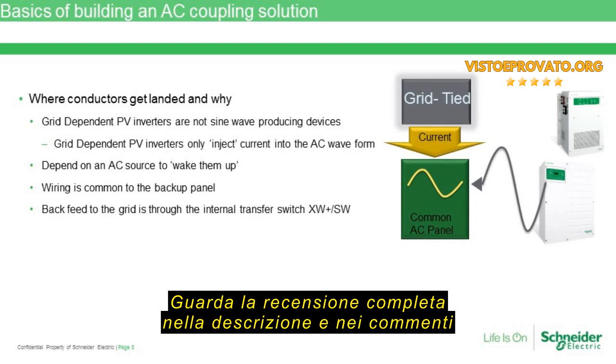then that grid tie inverter can start experiencing a frequency shift. And this is actually done on purpose by the XW Plus. So as the voltage on the battery starts to rise, the XW Plus is actually going to start shifting its phase from, say, 60 hertz to 60.1, 60.2, up to 60.5 hertz. And at that point, we're outside the parameters for the grid tie inverter, and it's going to kick out, which is fine. It's not really going to hurt it. It's really made to do that, to stop producing power when the frequency gets beyond a certain range.